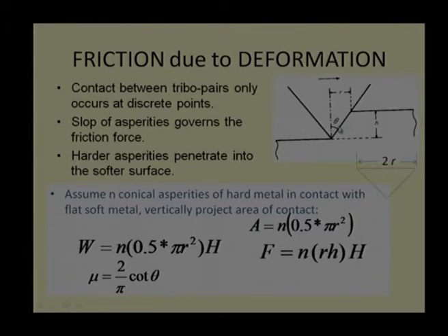The interesting thing is that when this cone is coming almost to the flat level, or theta is on the higher side, 80 degrees, do I need to use this conical theory? Instead of that, I will prefer to use the asperity as a spherical shape. As the cone angle increases, it will turn out to be more and more a uniform or flat surface at theta of 90 degrees, but lesser than that it will be some sort of spherical shape with round edges, which generally happens during the process.